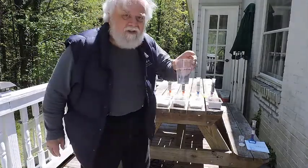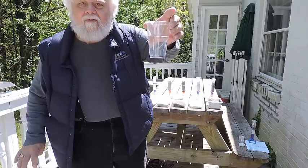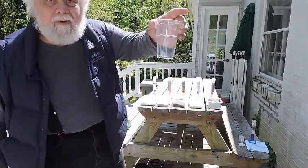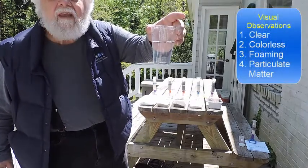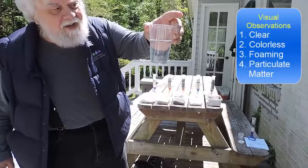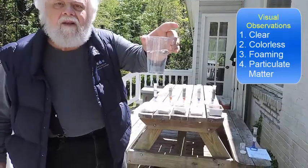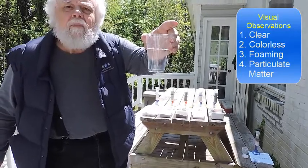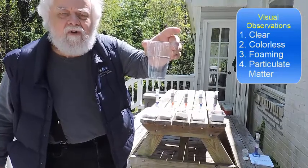This is clean water. You can see the four visual observations that we're making. First of all, is it clear? Can you see through it? Yes, it is. Is it colorless? Yes, it is. It doesn't have any color to it. Does it foam? No, it doesn't. Clean water is not supposed to foam. And lastly, is there any particulate matter in it?